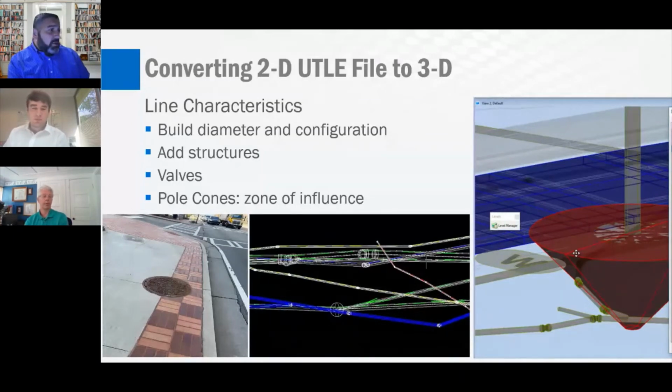The only above ground evidence that there is a telephone duct bank along a project, in most cases, is a telephone manhole, depicted here in the left-hand photo. So this is what we typically see. This is what's actually below the ground, and then we have the information all shown on the 3D model as well.